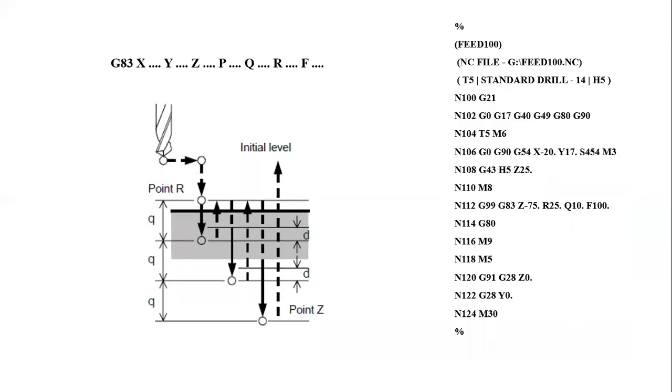The drilling method used is the back drill, in which after every 10 millimeters of drilling depth, the drill bit rises above the workpiece to remove the chips. This is when chip data was collected. The drilling program is shown in the picture.